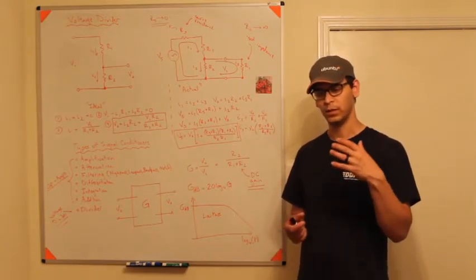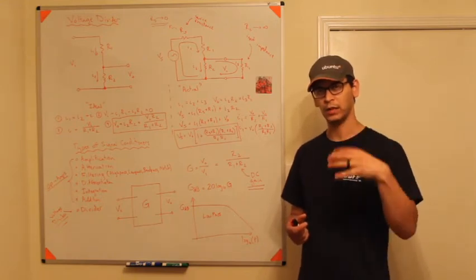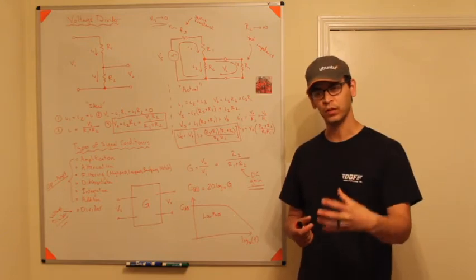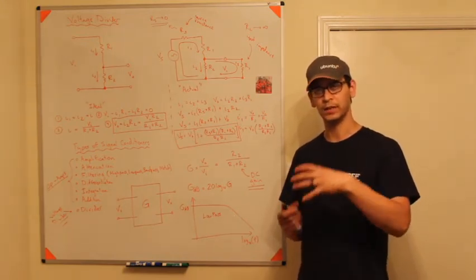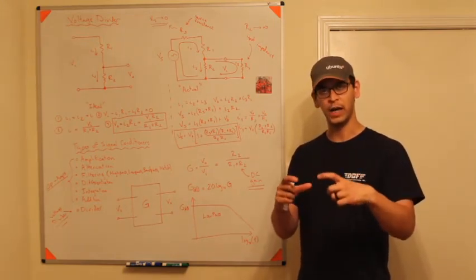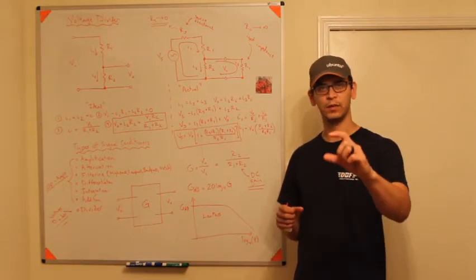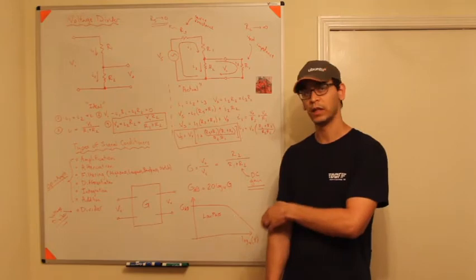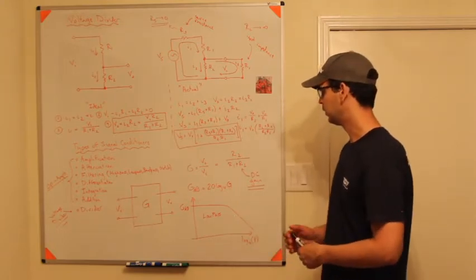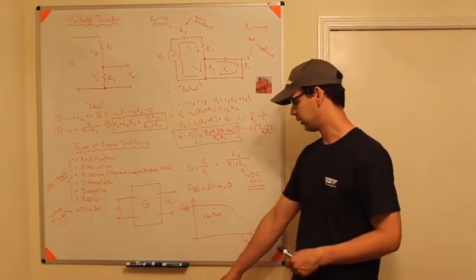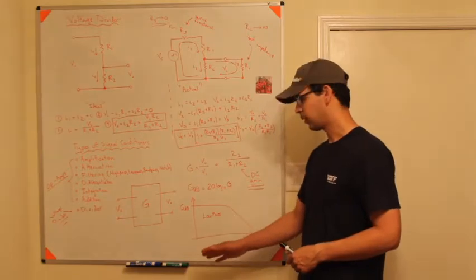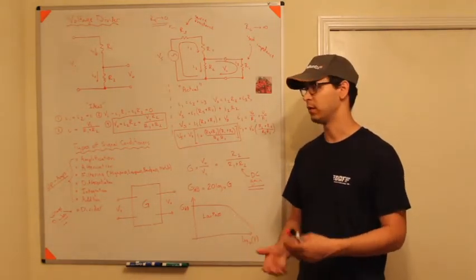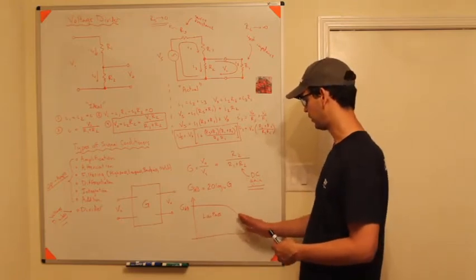And so you'll need some sort of AC to DC converter that will convert that signal from AC to DC. Usually there will be a box, or a lot of times a USB port thing you'll plug into the wall, and those will convert to direct current. So these signals here are 60 hertz. There are other things that have frequency content to them. They oscillate, and you might want to filter that out.